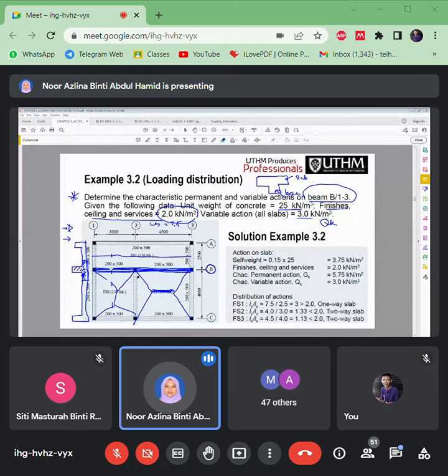So if you look here, this is how the loads of the slabs transfer. That means half of this panel 1 is transferred to this beam B, and these portions of triangle will transfer to this beam, and these portions of trapezium will transfer to this beam.